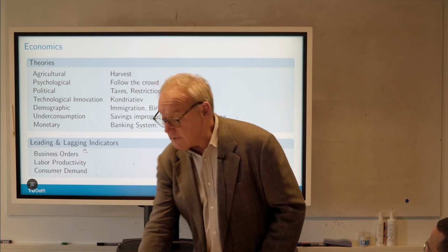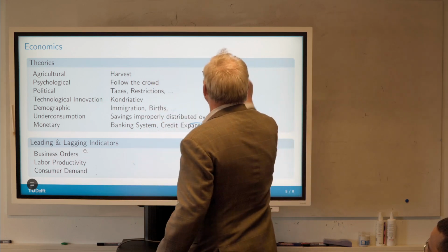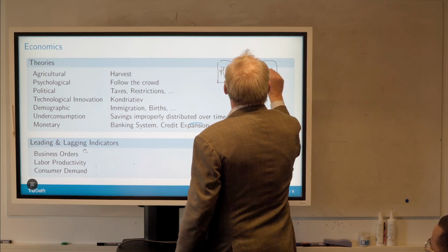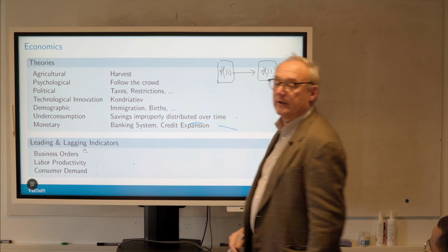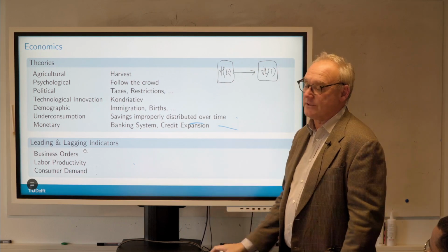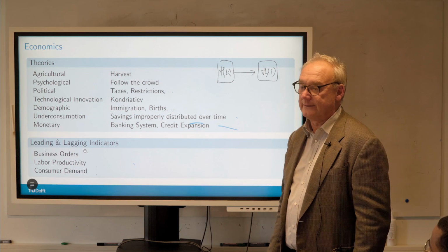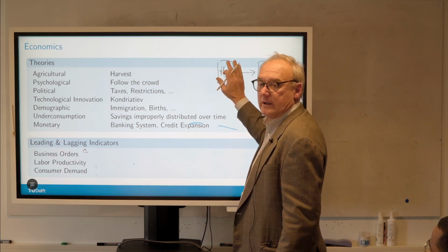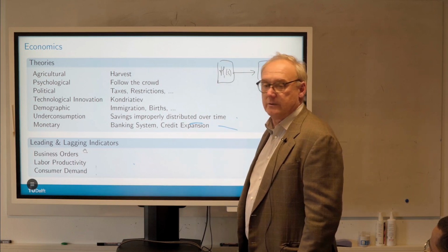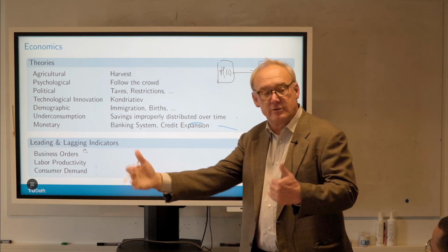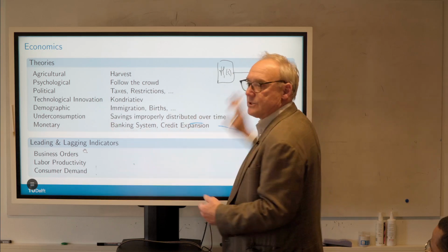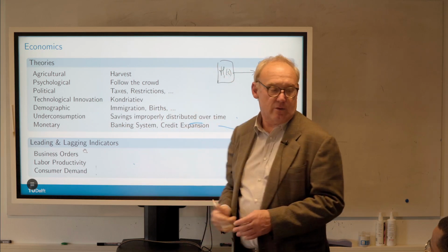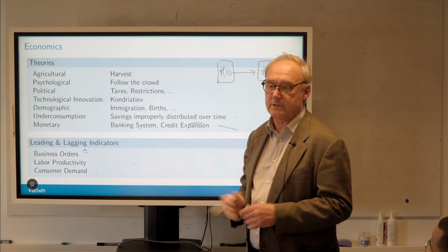Now, even in systems theory, you've got to be careful. You can't just take two blocks, with one transfer function here and another there, and then just say, hey, the total thing is the product, right? That doesn't work. You've got to have some humongous impedance here in order to make that work. Otherwise, you're not allowed to do that. And they do this impedance matching. They make one impedance really, really high so that this thing doesn't take much power from there. Otherwise, it's not going to work. You can't multiply it out. It gets more complicated.